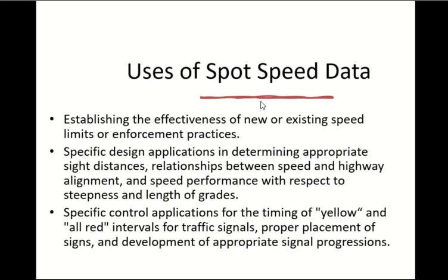And we know high speed will be attained in free flow conditions according to the driver. So whenever you are designing the radius of the highway, the gradient of the highway, vertical curve, a signal, a roundabout, all these things are designed according to the worst case scenario, which is the speed in free flow conditions. And you will get that from the spot speed studies.